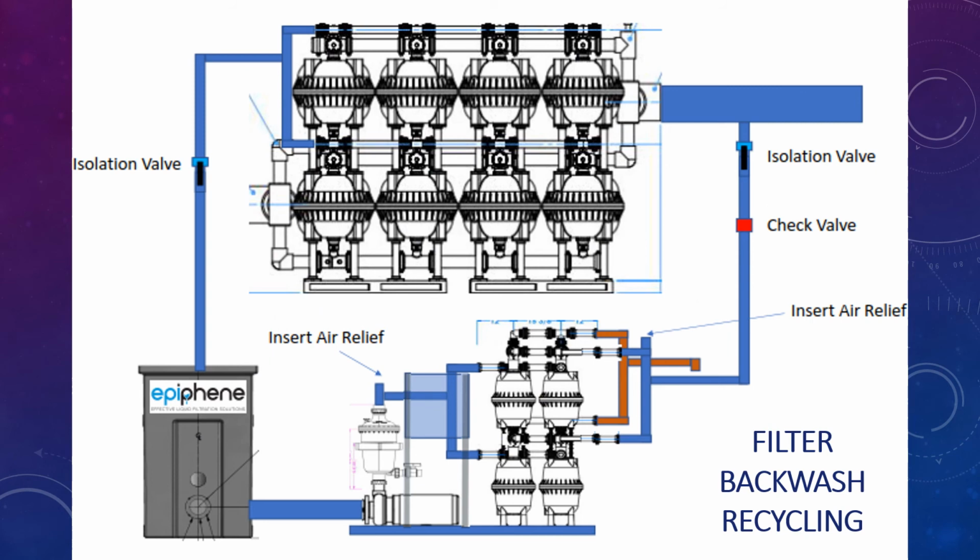Screen filters, or have set up their flush water to basically flush to a reservoir, and we've found a way, and we've actually tested it. But in this situation, I've only got media filters. We could have separators upstream, which would really help out this part of it. But we take all of the backwash water off of this, we run it through a gravity screen filter, and we pump that through a separator. And since these filters only require 50 gallons a minute, and each one will handle 100 gallons a minute for filtering and 50 gallons a minute for backwash, we're able to handle it with a single separator.